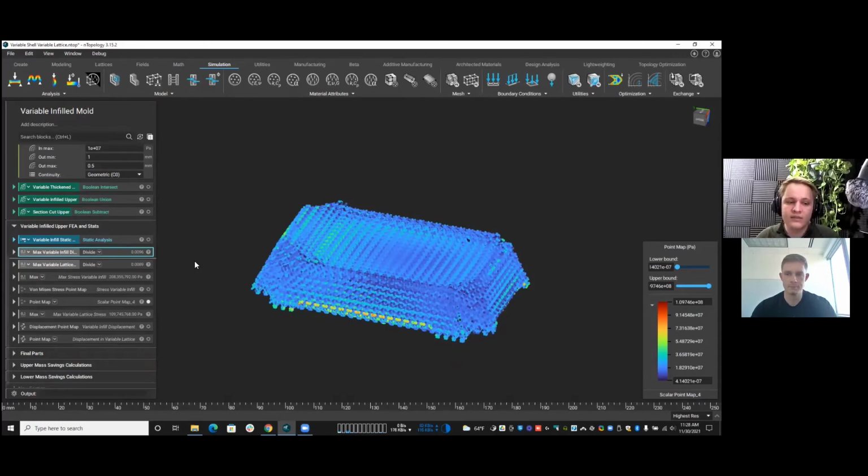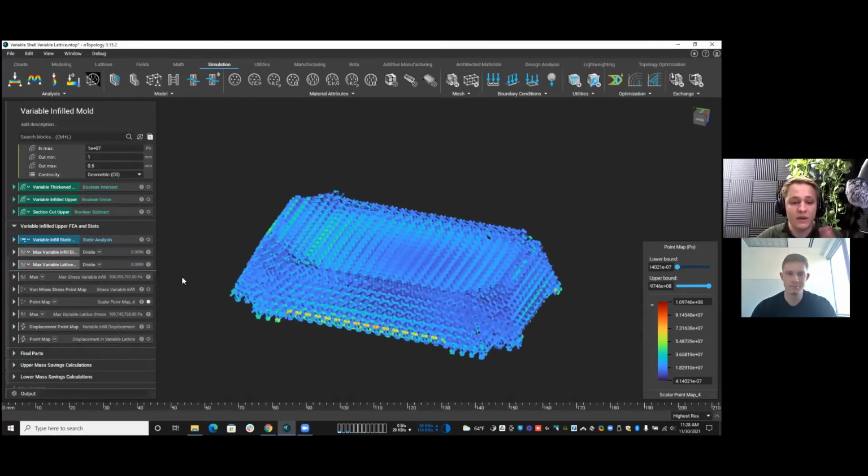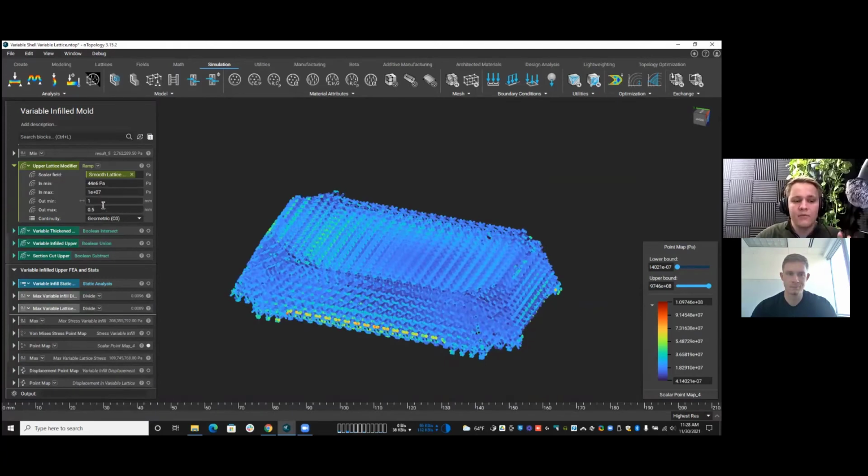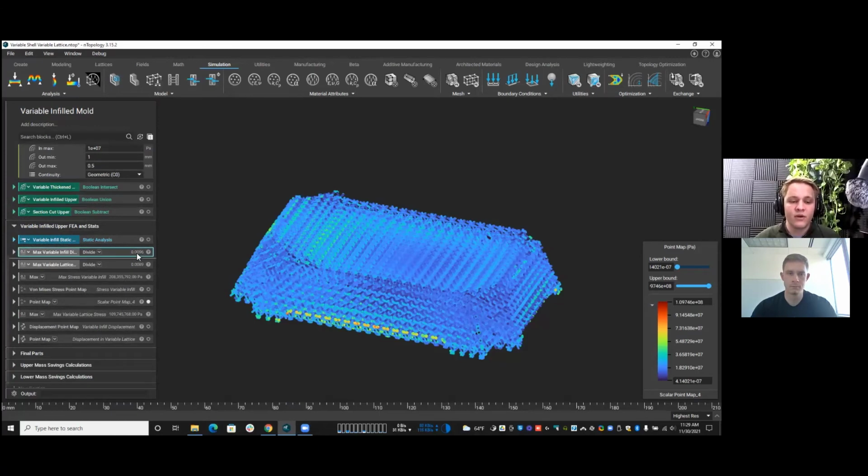We have hit our goal in this case, but I didn't hit this on my first try. I absolutely did not get this on my first go. It looks all nice because I have this all finished up and I'm just showing it to you, right? But from 0.5 to 1, that was not my first choice. I actually started off from 0.5 to 0.6, and then I reran and I saw, well, I still have about 11.8 thousandths displacement, right? That's not quite good enough. So I just kept increasing this number. Everything in nTop reran for me, including this FEA verification, and I just changed up this number until I hit 1, and I reached my goal of below 10 thousandths of an inch of displacement, right?